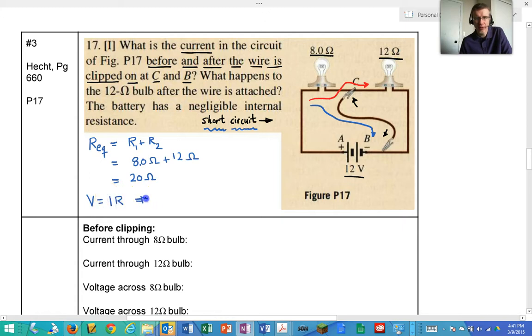Or, of course, put another way, the current, let me put a real proper I here, is the voltage divided by the resistance. So you would draw your little thing, just remind yourself, current equals voltage over resistance. So what I get when I do that, I would say there's 12 volts, that's the driving force on the circuit, divided by 20 ohms. And I think you would find that that's, let's see, 4 goes in, so that's 3/5 of an amp.